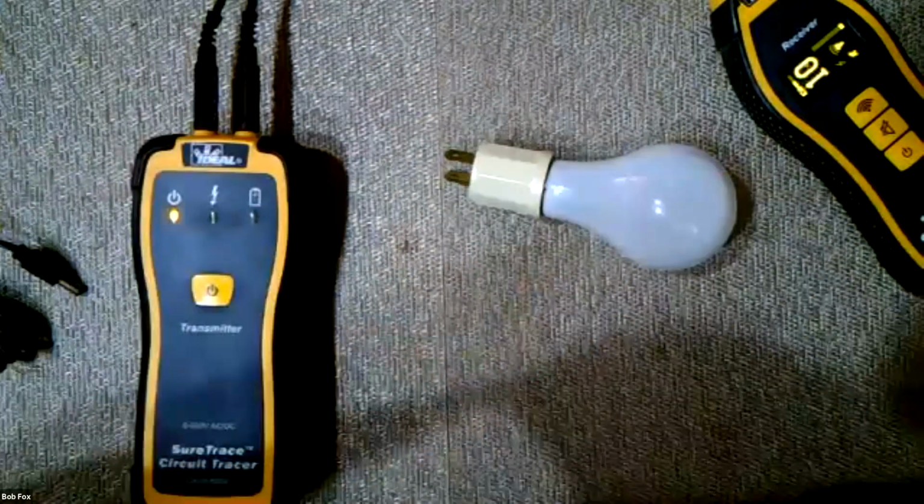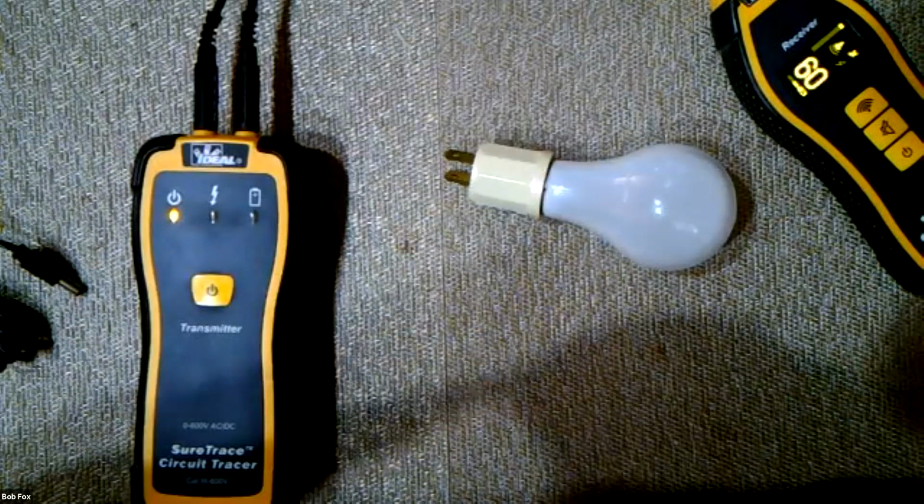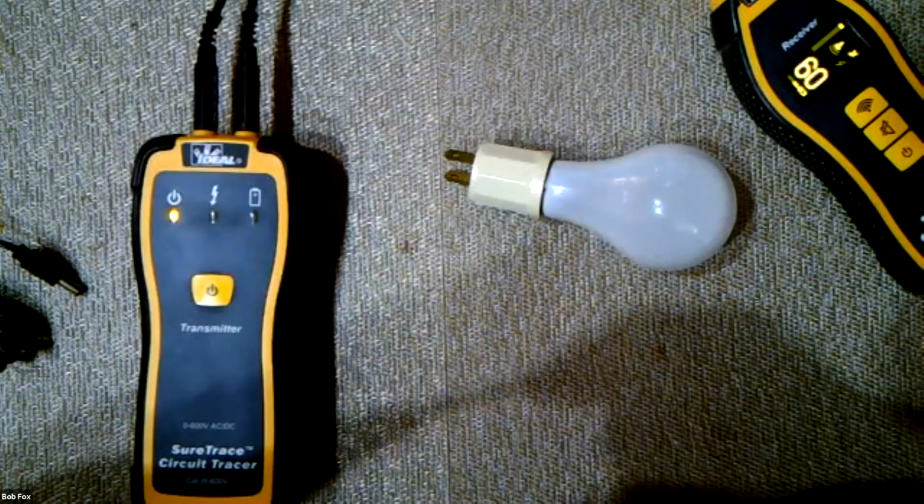The other part of it is that when you look at depth, I have an instance where I had an old farmhouse that we were renovating, and I had a galvanized water pipe buried 6 feet down, running from the house out to the well, and the UF power wire was buried as well. We had a crack in the pipe, so it had to be replaced. We had to find it. So we hooked the transmitter up with a vice grip on one end of the water pipe, and then we got one out to the other end at the well, and then with some TNM wire, hooked the other end up with a vice grip, ran it back in, and hooked the transmitter up on it. And the signal strength was really strong.